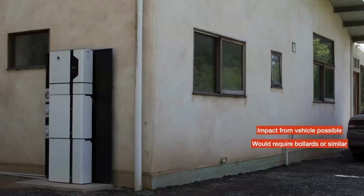This is the same system, but just looking down the side of the house, looking for other locations. So this is actually me walking around my house, trying to find somewhere to put a BESS or a battery system. Now, that's a driveway, so the potential for impact from a vehicle is a consideration. There's no actual requirement in 5139 for bollards, but mechanical protection is covered under AS/NZS 3000. So if there's a likely impact based on the location and there's an electrical hazard, you still need to have appropriate mechanical protection. In the case of a battery in a garage, that may well be bollards.